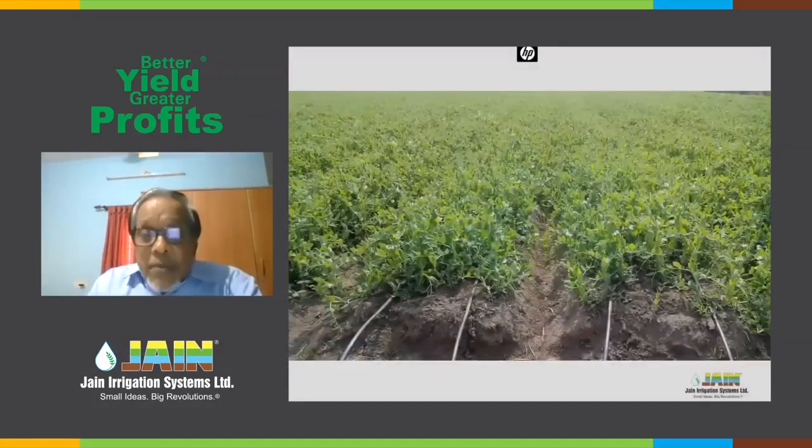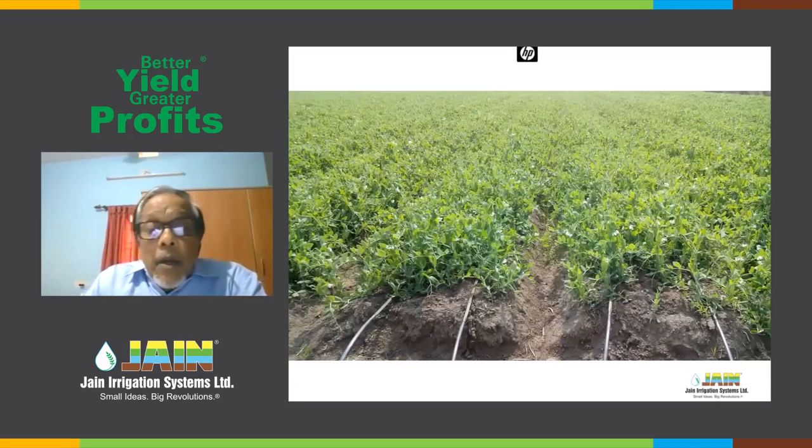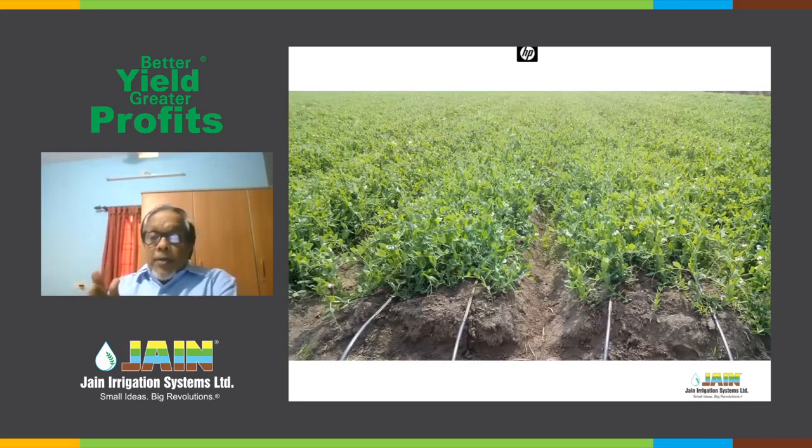For example, now I'll show some examples. See, this is from Punjab. You have a typical alluvium type of soil, sandy loam soil basically, and there is a certain spread. You can get about 25 to 30 centimeter spread, and the two drip lines are at 75 centimeter, and the spread from one drip line up to about 35 or 40 will coalesce with the other drip line. In effect, the entire bed will get uniform distribution, and as you can see, a very uniform crop.